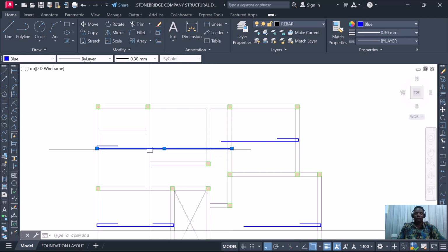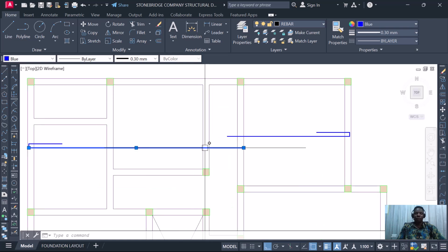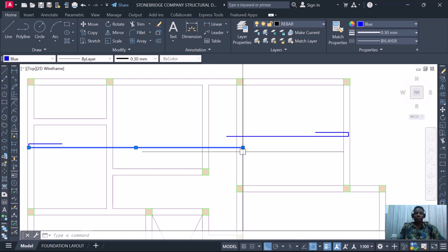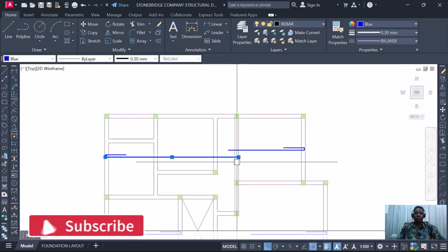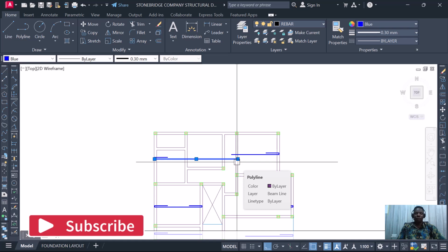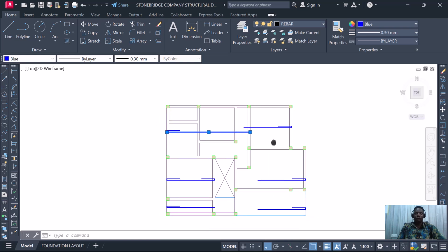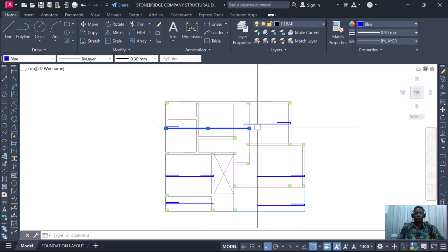But what I normally do from experience, when I have a beam like this, in the bottom reinforcement I always lap it at the joint here. At the top I always lap it at the middle span. Why? Because at the middle span, the tension is high along the bottom, and considerable along the joint, but at the top there is high tension along the top area, and less in the bottom. So for me to do that, I just have to do my lapping inside the beam here.